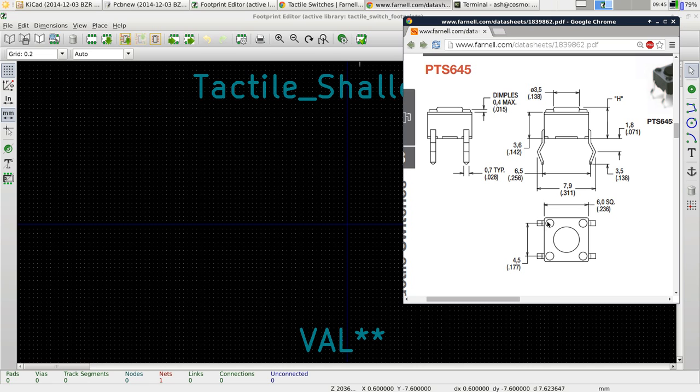So what I think we want to do is we will probably want to put the holes, since that's the edge there, if we put the holes at 6 mil apart, the hole will be centered there, and then that's actually very, very narrow indeed. You know, that's probably 0.2, 0.15 mil or something. And if we've got a 1 mil wide hole, then that will easily be encompassed by it.